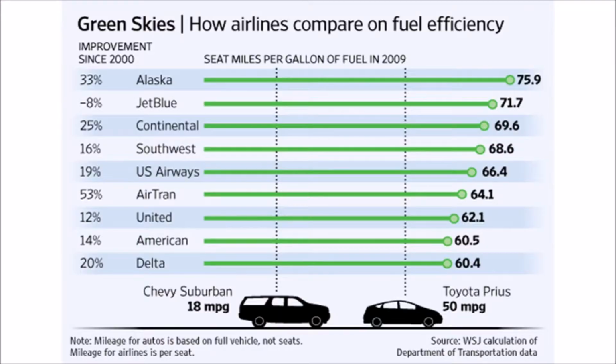Usable fuel is the fuel available for flight planning. Unusable fuel is a quantity of fuel that cannot be safely used in flight. Gallons per hour, abbreviated as GPH, is the amount of fuel consumed per hour by the aircraft. On larger aircraft, describing fuel in gallons is unnecessarily complex, and pounds or kilograms per hour is used to describe fuel consumption.